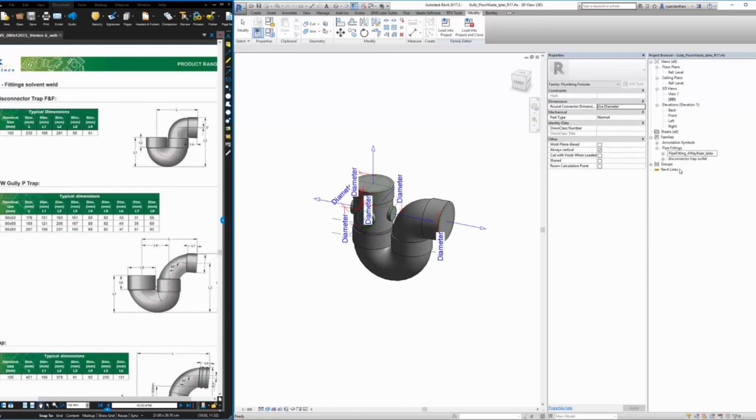So when you go through and you do all of your schedules to put on your drawings and you want to schedule out the plumbing fixtures, so Brisbane City Council, Gold Coast City Council, for example, require a fixture schedule. The floor waste gullies will show up and they show up as a single fixture.